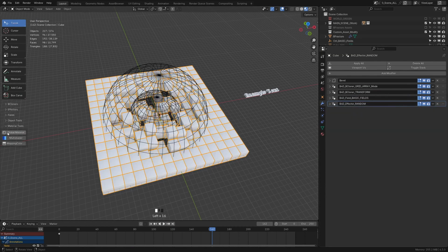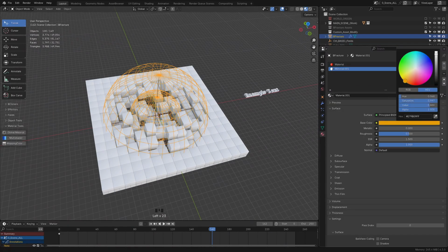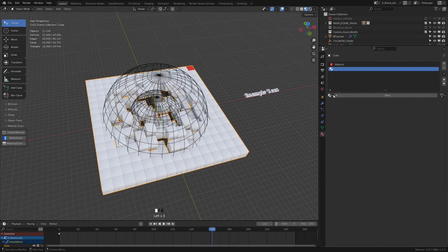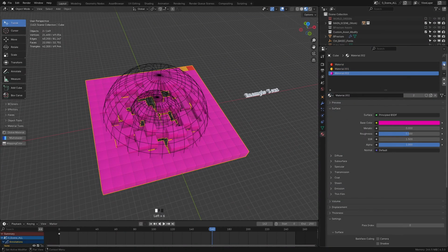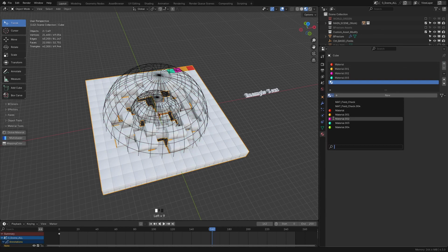I deleted that modifier and I added the multishader. The multishader adds in order the materials in the material slots to each instance. So I created a few simple materials, and then I added them all to the BCloner material slots. As you see, by default it only adds the material slots in order and repeats the last material.